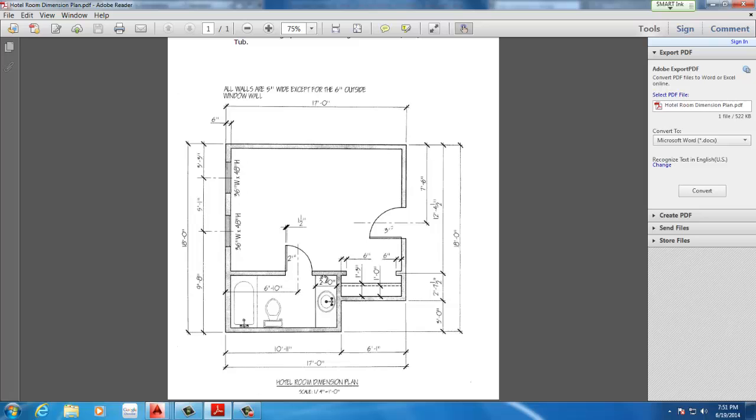What I really want to do is the end from the end of the wall. So I have to remove 2.5 inches, since that wall right there is 5 inches thick. Removing 2.5 inches would give me 2 feet 5 inches and 3 feet. So together they'll be 5 feet 5 inches. So that is my bathroom size.